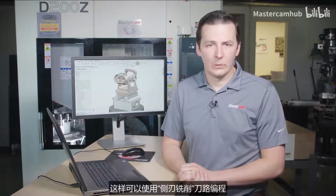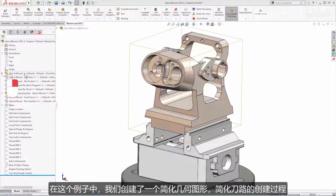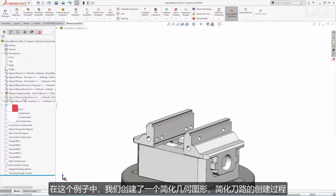The tapered flange on the front of this part was created as a lofted solid, which makes it possible to be machined using a swarf toolpath. In this example, we've created a simplified piece of geometry to make the toolpath creation even easier.